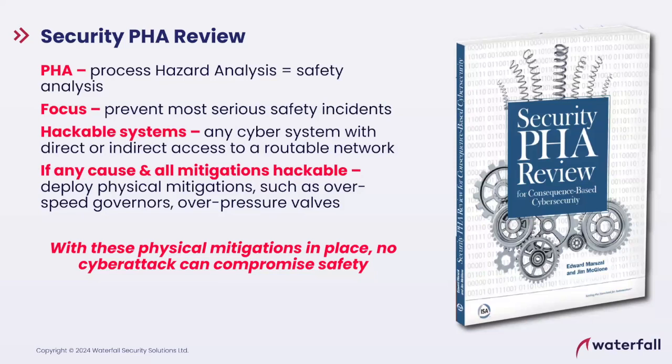Okay, if any of the triggers are hackable, then look at the mitigations and ask the question, are all of the mitigations hackable? And you look at them and say, well, the HMI is hackable. The safety instrumented system is software, it's hackable. But the mechanical valve is not hackable. Well, then we're good. It's not possible for a cyber attack to bring about this outcome. On to the next row.